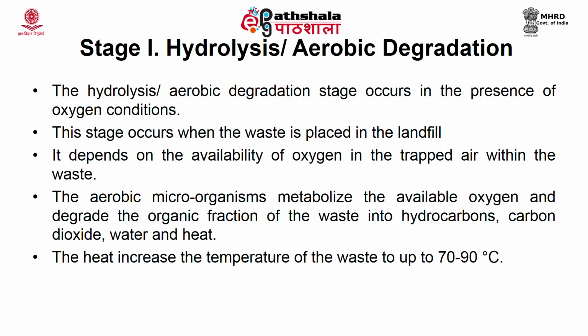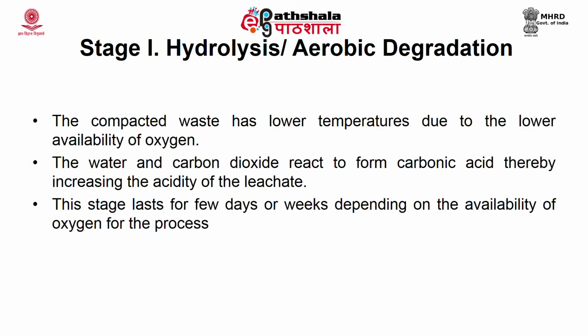Now, the microorganisms are aerobic and they require oxygen. What happens during this process is, since you have oxygen and aerobic organisms, they multiply, they grow, they have substrate also, they degrade, and they increase the temperature up to 70 degrees Celsius. The products produced during this aerobic degradation or hydrolysis are mainly carbon dioxide and water.